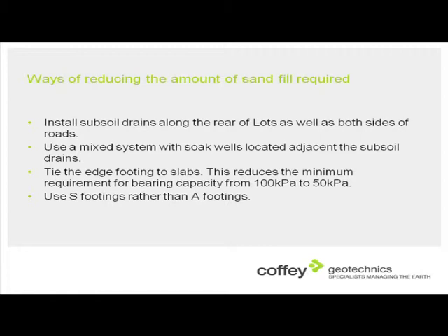Some ways we could consider to reduce the amount of sand fill required, if we want to keep having backyards where we don't get mud on our feet: well, we could put subsoil drains along the rear of the lots, and I'm sure there are those who'll say that's going to be really difficult in terms of maintenance, and I accept that, but it is a technical solution. We can use mixed systems for soak wells. Instead of putting enough sand there to be able to use soak wells, we could have soak wells take the first flush of the storm and let the overflow go to the pipe drainage system.